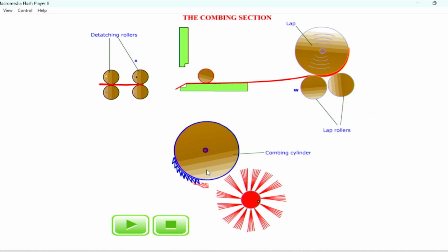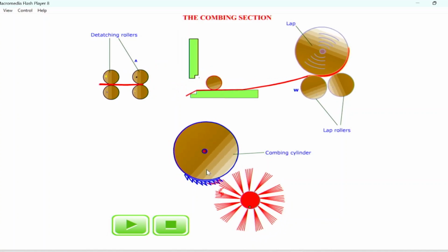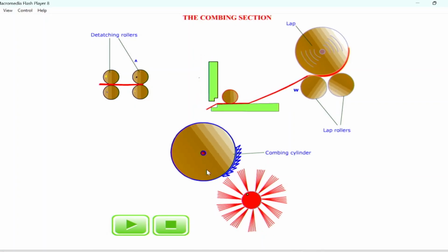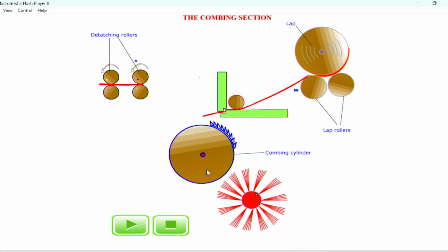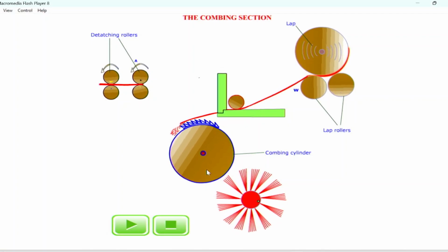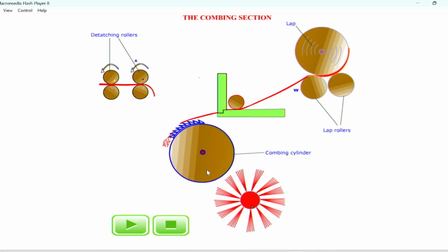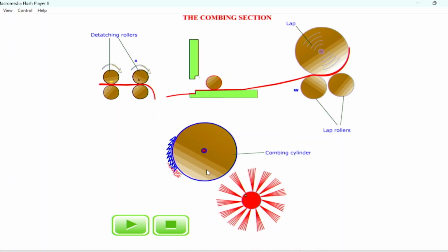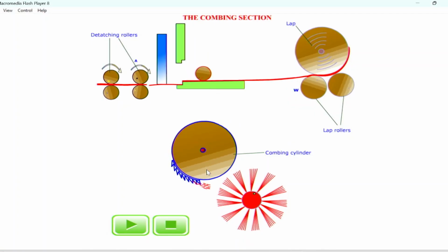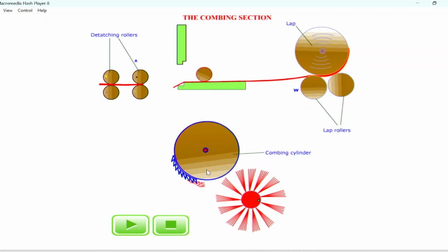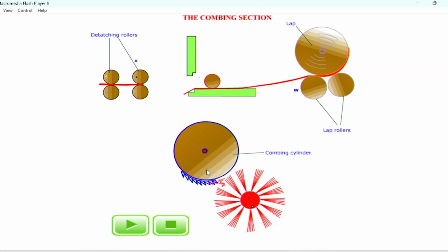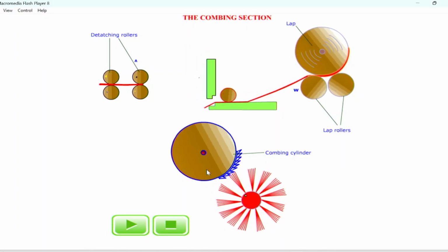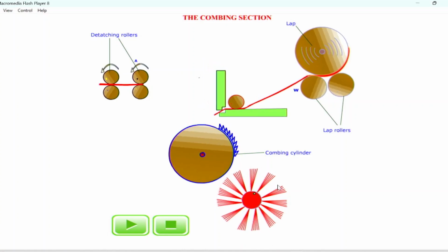Now it is going back once again, the nippers are coming back, it is backward feed and feeding is taking place at this time, and then the nipper closes. As soon as the nipper closes, the cylinder comb is combing the leading portion of the fringe, and whatever noils were there, the short fibers, are being brushed by the brush roller, shown in the red color.